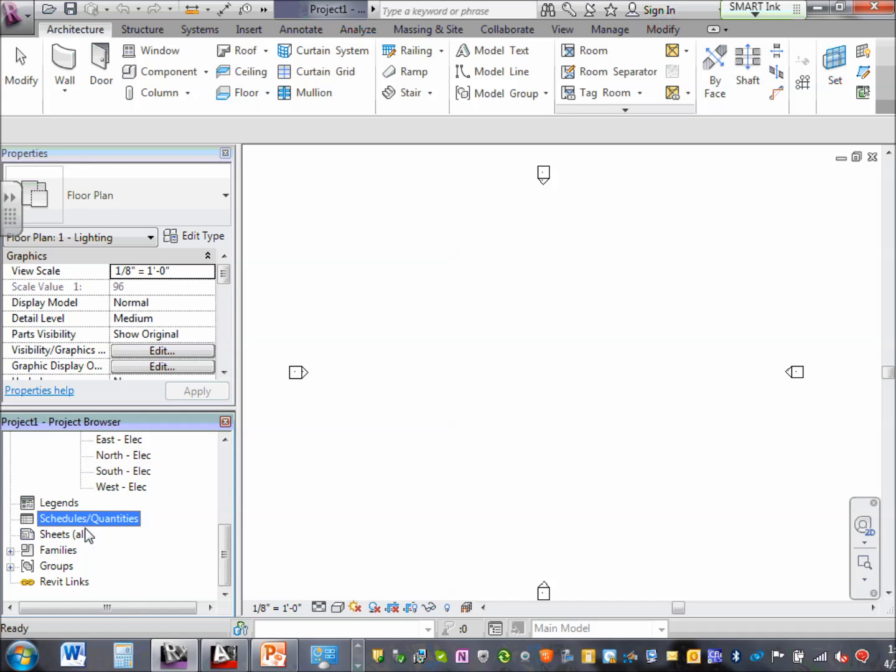Can you guys see schedule? You remember the panel schedule? Look at the panel schedule right there. See that? All these panel schedules? You'll see them right here. These are all panel schedules. When you're running panel schedules, you hit the button, it runs a panel schedule for you, and guess where it goes, drops it, right there. So if you're looking at all these views, these schedules, where are they located? Under schedules. That's a piece of cake, right? Easy. Easy to find, yeah.